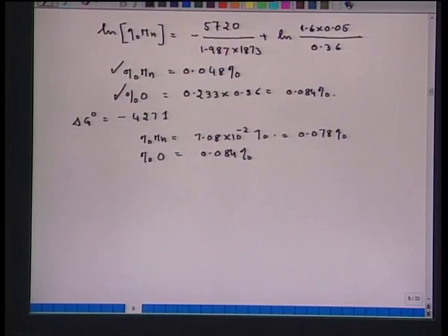So, all that it says is that manganese can be oxidized very easily under steel making condition. The sources are different, therefore, you are getting different values of manganese, but it does not matter at all, because all that will depend upon which source you have used to calculate the value of manganese and what values you have substituted. I have substituted the value of gamma MnO as 1.6, you may get a different source which may have different values. I calculated the value of activity of FeO as 0.36. From another source you may get 0.4 or 0.5, because there are several sources available, but it does not matter. All that it says is that manganese can be oxidized very easily.